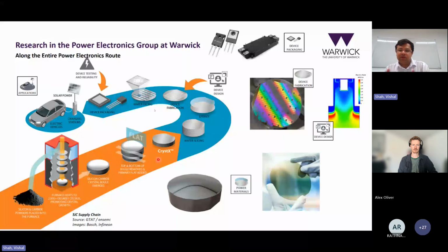But also the damage to the device, or the structural quality, may be quite damaging as well. But then what you'd like to do is take your device, your layers, your substrates, which is over here, which has been sliced, and then perform epitaxy on them. You then want to take those, perform device fabrication, go on to do device and wafer dicing, package those devices, and then put them into the end application.